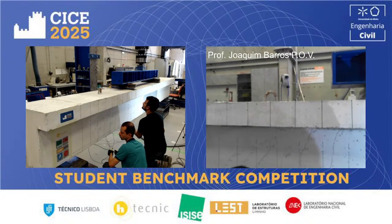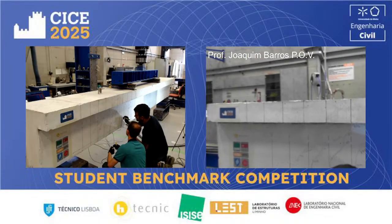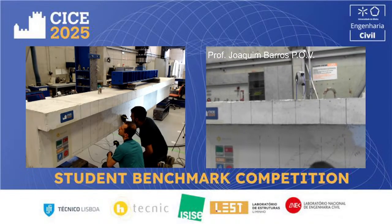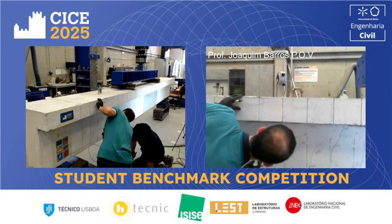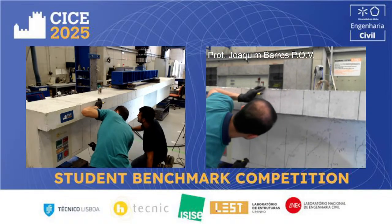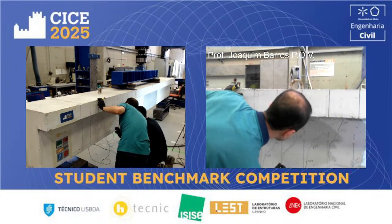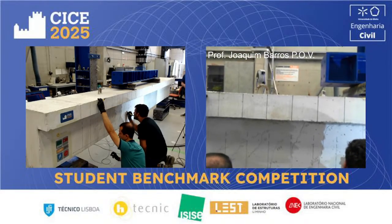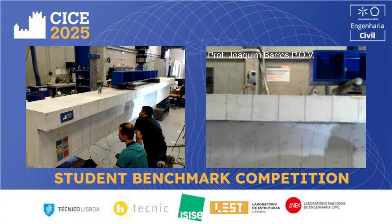So the principal stresses are rotating, 280, and the crack is also rotating when it progresses to the top. They initiate in the soffit as vertical, 281, but then the inclination changes during the loading process.